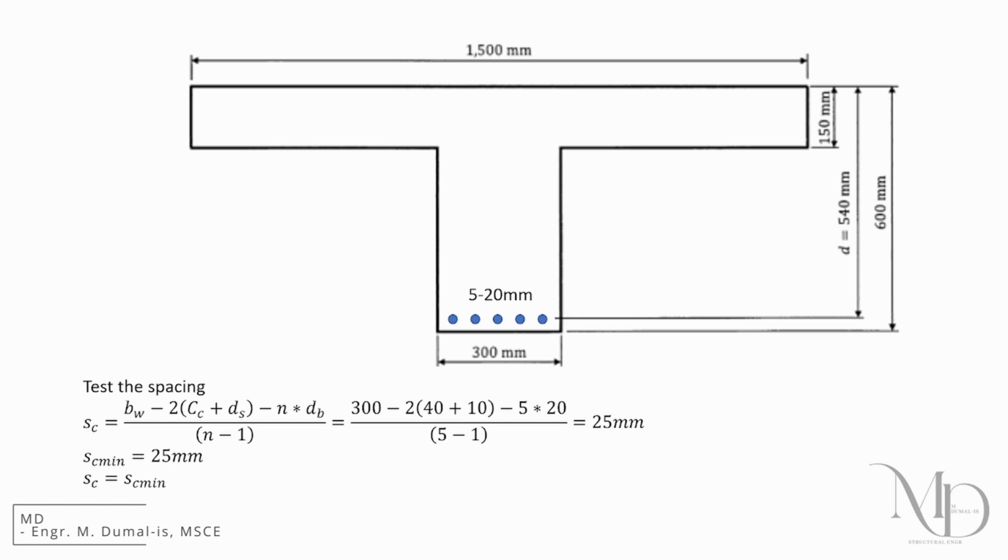At this point, we can go a step further and check the spacing of the reinforcement. Now, you've got a couple of options here. You can either directly compare the actual bar spacings with the allowable limits, or you can calculate the minimum and maximum number of bars that can fit per layer based on code requirements. Either approach is perfectly valid, so feel free to use whichever method you're more comfortable with, or whichever makes more sense for your design process.